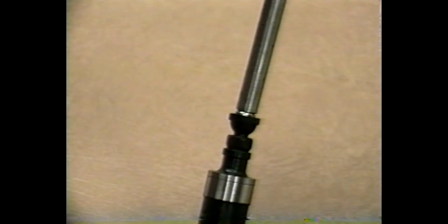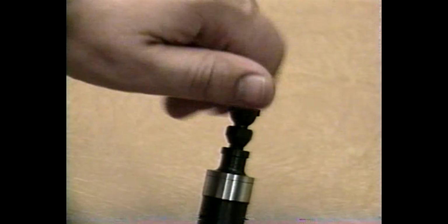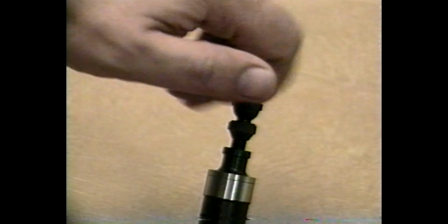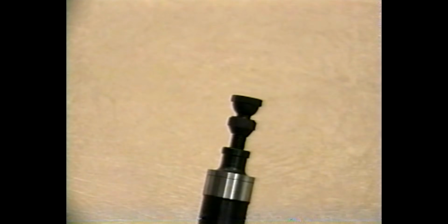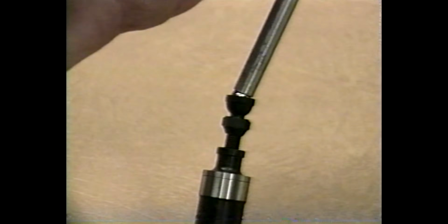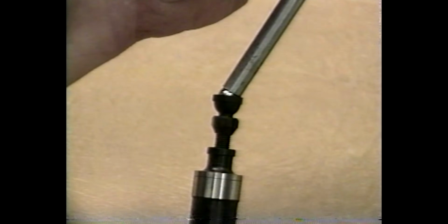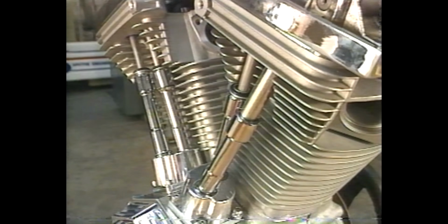There are also some negative effects that result from the use of solid adjustable lifters. By raising the seat for our solid push rods higher, we start to dramatically increase the angles between lifter and push rod, forcing the push rod further out of alignment and causing the push rod to rub on the push rod tube. In addition, the stresses experienced by the push rods during operation are dramatically increased as the angles between lifters and push rods increase.